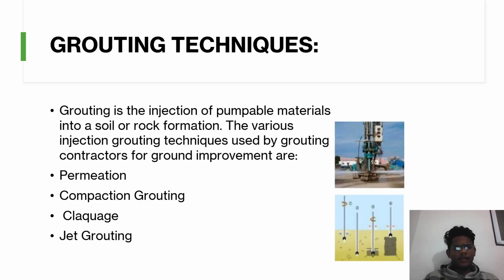Grouting techniques. Grouting is an injection of a pumpable material into a soil or rock formation. Various injection grouting techniques are used by grouting contractors for ground improvement: permeation grouting, compaction grouting, claquage, jet grouting.